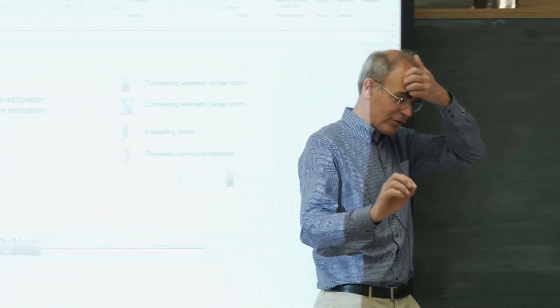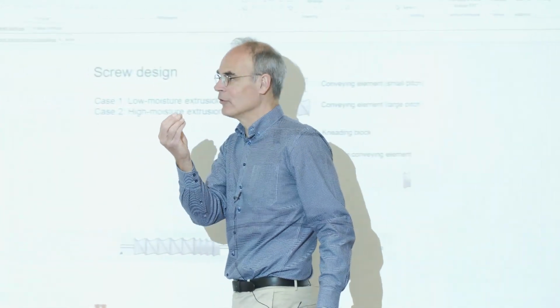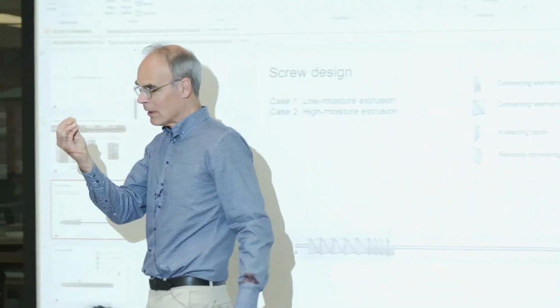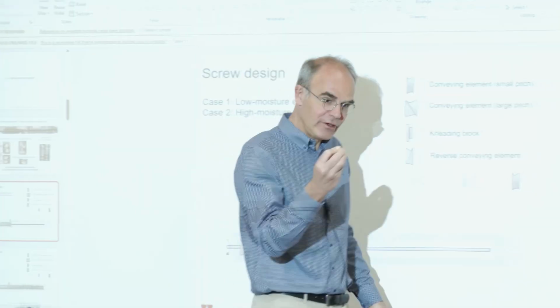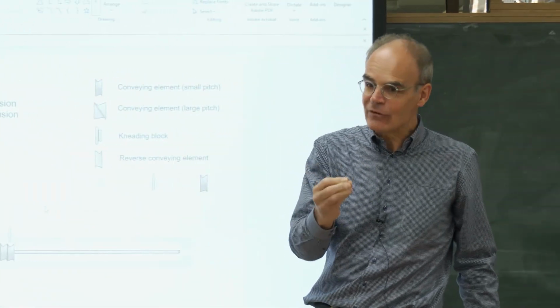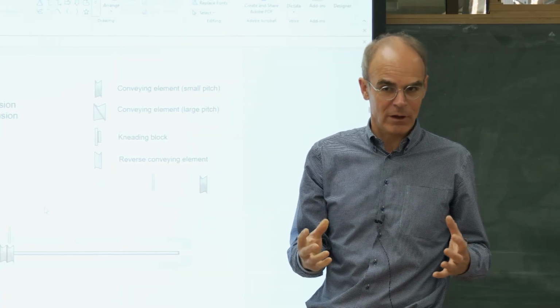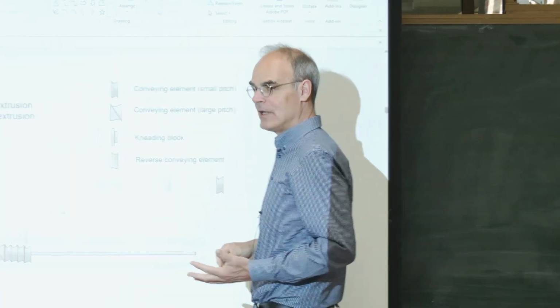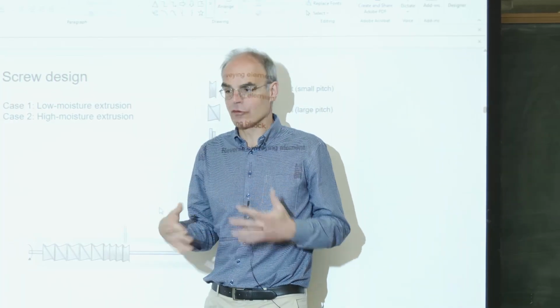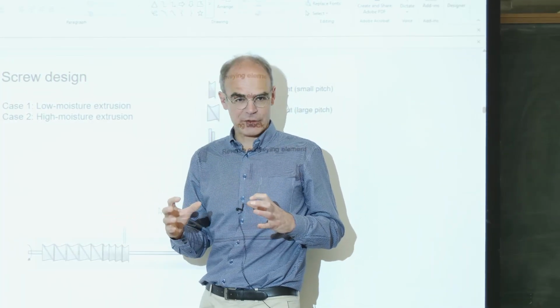And especially also for starches, because if you have the starch granules, these are little nasty, little hard balls. You really need to gelatinize them and then they become soft and gooey. Now an extruder can handle even that hard material, but it's also not good for your extruder to run almost abrasive material in that barrel.